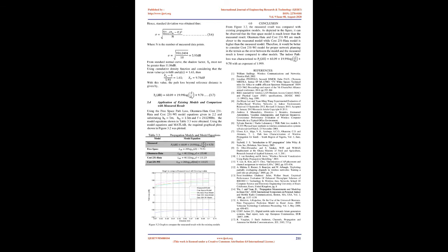The model increases accuracy of the propagation estimation, but it is more complex when compared with the Okumura-Hata model. The model allows estimation from 20 m instead of 1 km for the Okumura-Hata model, and mean path loss is suitable for the model. COST 231 is restricted to the frequency, F, between 800 MHz and 2000 MHz, transmitter height, H, between 4 and 50 m, receiver height, H, between 1 and 3 m, and a transmitter-receiver distance, D, between 0.02 and 5 km. Figure 2.6 illustrates the above stated parameters to be taken into consideration when conducting field measurement that is to be analyzed using the COST 231 WI model.